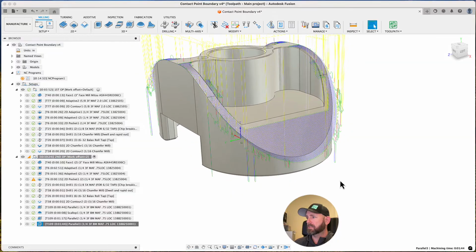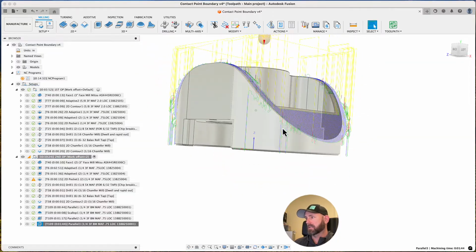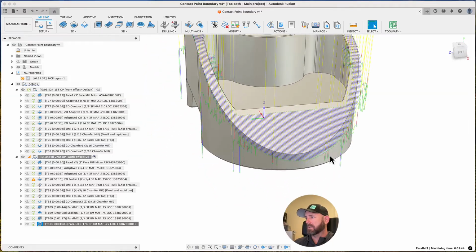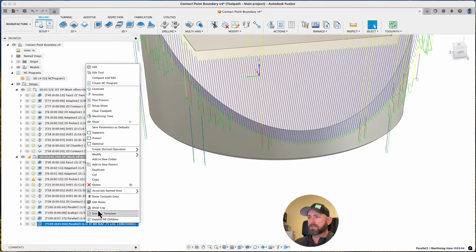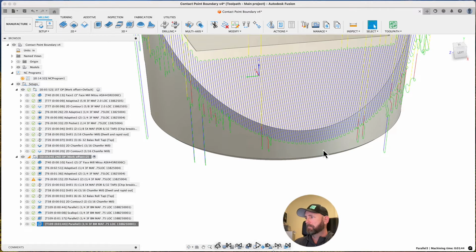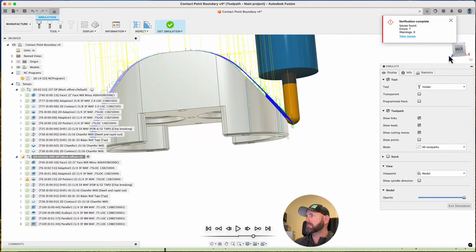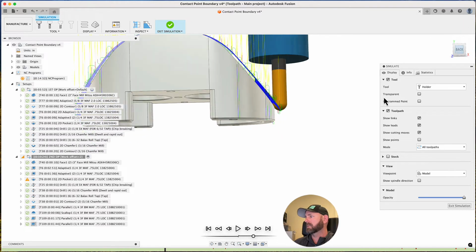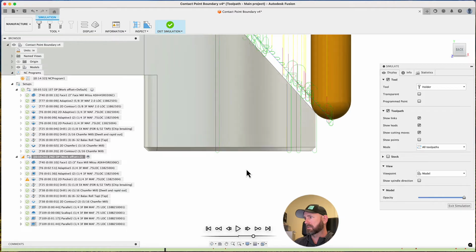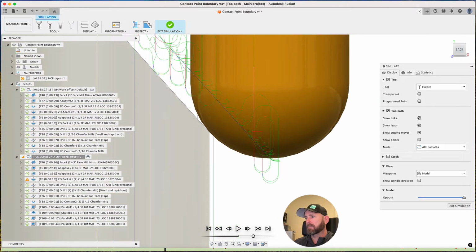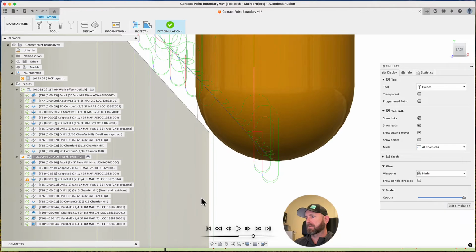And this is scary, right? This looks like we're going to go do bad things. I want to encourage you to look past the waterfalling of the toolpath, and let's go do another simulation and see if we at least, looks like we maybe solved a problem and created a problem. So we'll dig into that and understand it. We'll click here. Verification's got an error. It's a nice thing to tell us because we're going to collide down here, right? Well, we fixed this problem, right? It looks like we're actually machining the whole thing.